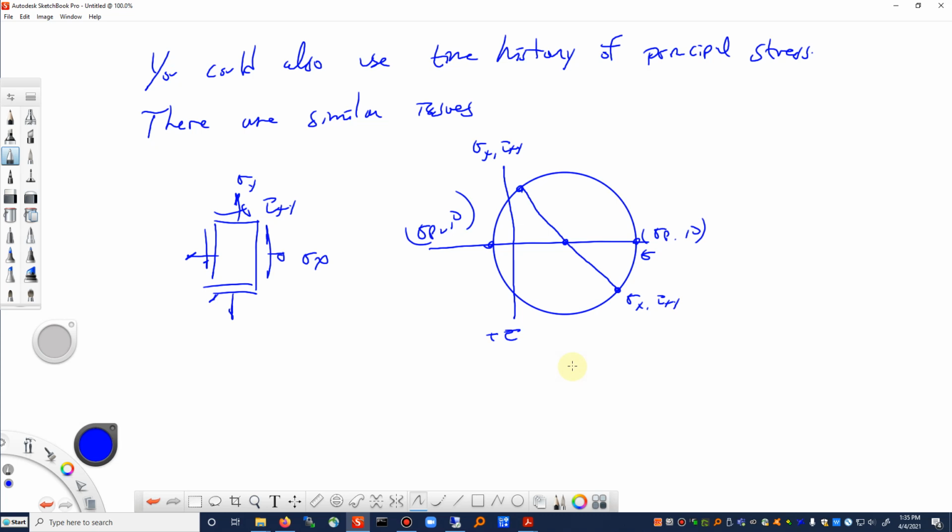Now there are some other multiaxial type calculations, Dang Van and so forth, that have arisen since the critical plane approach, but from a pedagogical perspective, from a perspective of what goes on from the materials point of view, I think the critical plane approach is a really solid approach to use. And so we'll get into those details, like I said, in an upcoming lecture.